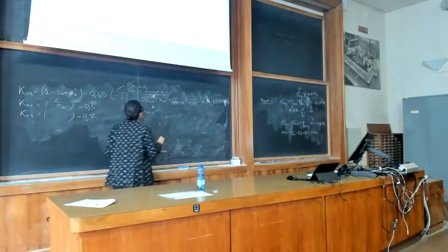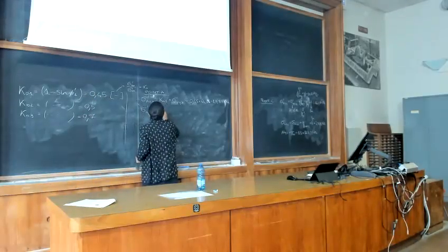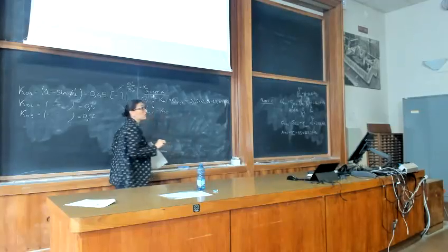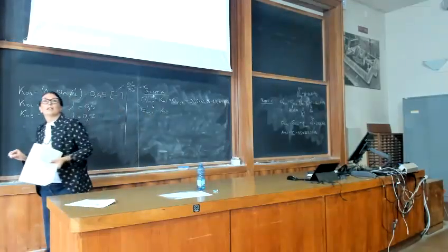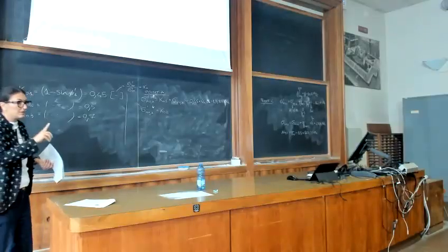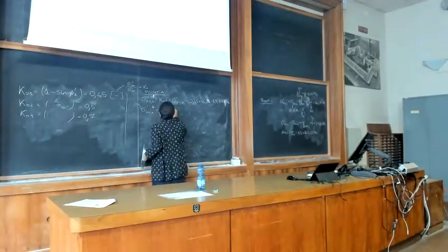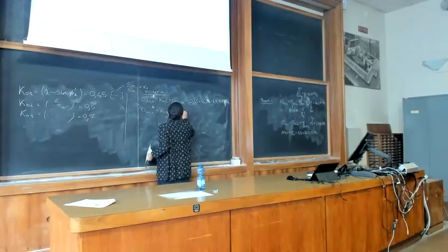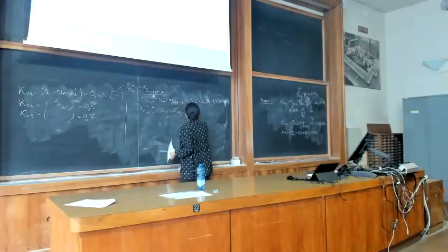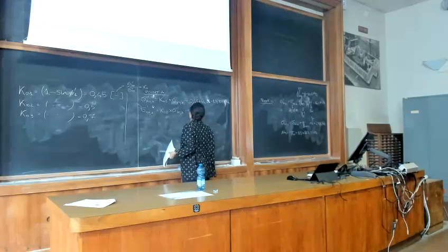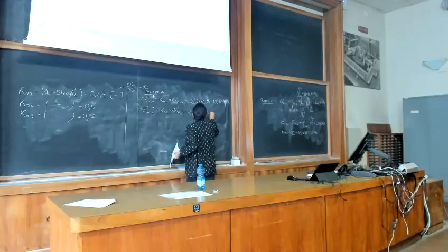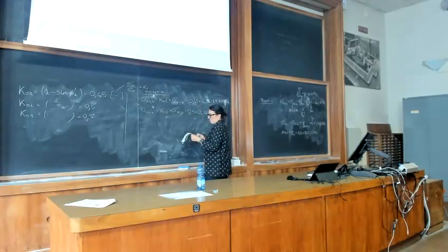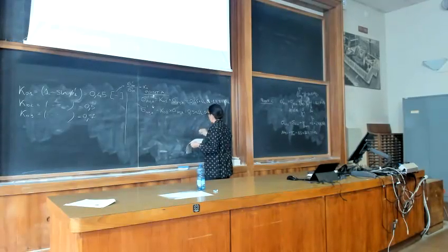So just below the discontinuity, we have to use K02, because this is the horizontal earth pressure coefficient at rest for the second layer, and you multiply this value for the same stress state, which is sigma dash V naught in point A. Okay, so 0.5, which multiplies 44.16, and you obtain 22.08.